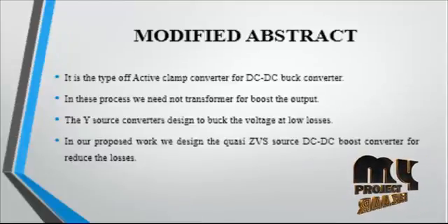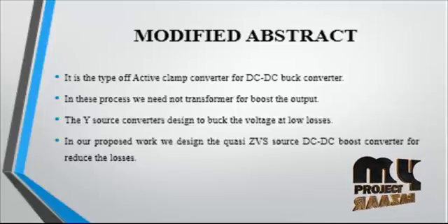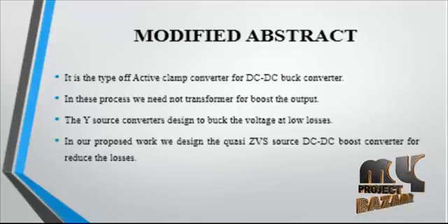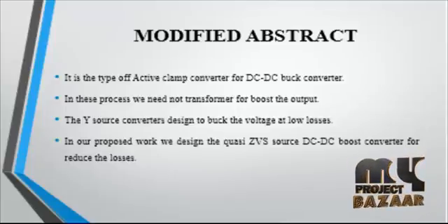Now we are going to discuss our product abstract. Active clamp DC to DC converters are pulse width modulated converters having two switches, featuring zero voltage switching at frequencies beyond 100 kHz. Generalized equivalent circuits valid for steady state and dynamic performance have been proposed for a family of active clamp converters. The active clamp converter is analyzed for its dynamic behavior under current control in this paper.